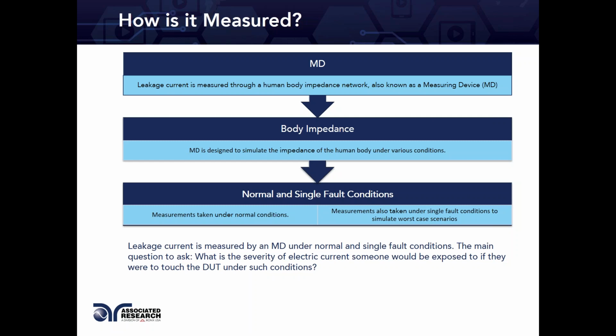Manufacturers of electronic products are responsible for making sure that their devices are safe to use by the end user, especially when you're a medical device manufacturer. Your devices will be used in hospitals with patients, and that brings the risk level a little bit higher when a patient in the hospital is touching some sort of electronic device. There's always a chance that something can go wrong inside the device, and the patient can be exposed to dangerous levels of leakage current.